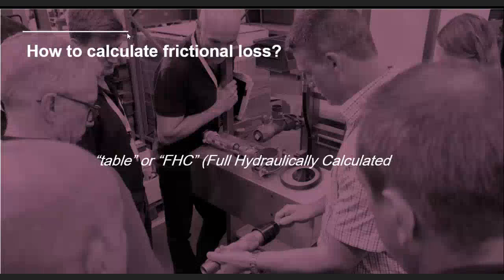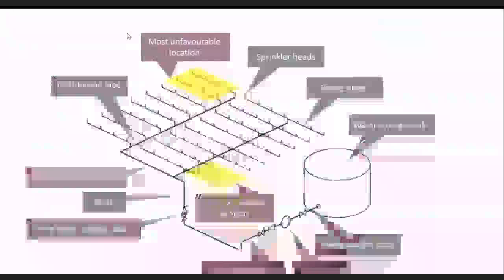If we go for full hydraulically calculated, essentially what we're using is a computer program, and we're working out the frictional losses everywhere. We're working out the pressure everywhere, and we can actually see the pressure at all the different heads. Because it's a computer model, once we've built it, we can interrogate it. We can say, okay, what happens if I swap this pipe over? What if I use this size instead of this size? If I add an extra elbow here, what effect does that have on the calculations? So we can fine tune it, get it as efficient as we can. Table method is a lot quicker. FHC is more adaptable, editable, and we're allowed to fine tune it. What I'll be talking about now is mostly the pre-calculated table methods, but the FHC is doing the same thing in the background as a computer program.